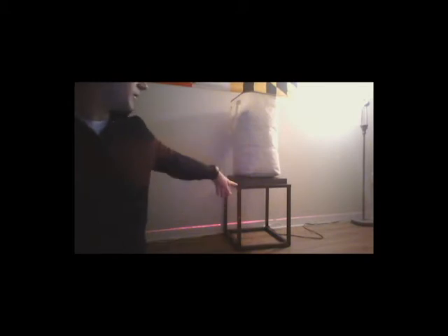Alright, so this is my setup for testing my LiDAR system. It's up here. And so the laundry bag is positioned on this table. The laundry bag is approximately 5 feet from the LiDAR sensor, and the LiDAR is 6 feet from the wall. The laundry basket itself is about 2¼ feet high and about 13 inches across, and it is approximately 2 feet off the ground. And so we're going to be scanning this at increments of 2 degrees from negative 20 degrees to positive 20 degrees.